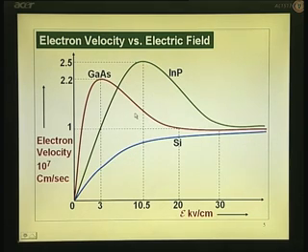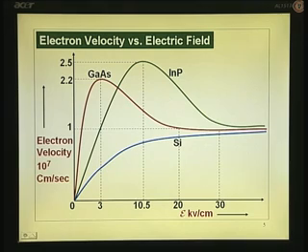You can call this the electric field corresponding to peak velocity. We refer to it as E peak or transition electric field, and that is almost about 3 times the field here. And notice also saturation velocity is not much different, nothing much to boast of. You cannot say gallium arsenide has a very different saturation velocity than silicon, but the point to notice is there is a wide range of electric field over which the fields are high.